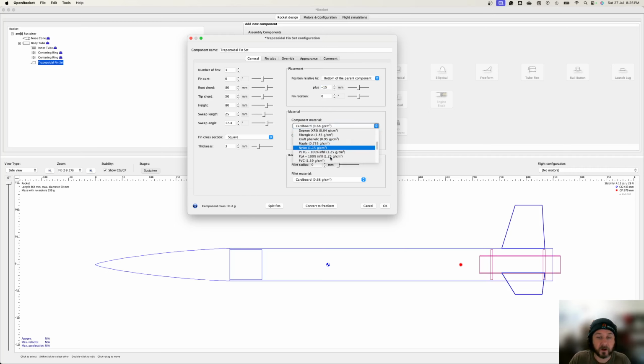They're not going to be cardboard. They're going to be PLA because they're going to be printed. We do want that. Now the thickness of them. We had a team do 2 mil last year. I think they might have snapped. 3 mil is kind of the norm and the standard go-to. We did have another team do 4 or 5, and I thought they looked pretty good.